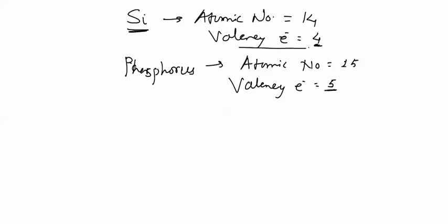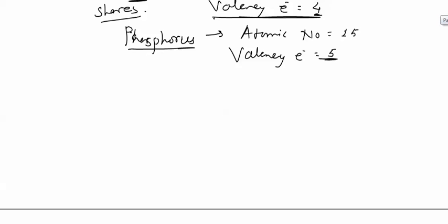In silicon, earlier we have seen the bond structure in which every silicon atom shares its 4 valence electron with adjacent 4 silicon atom. Now a phosphorus atom will be added which has 5 valence electron instead of 4. So we will see exactly how the bond structure will look like.